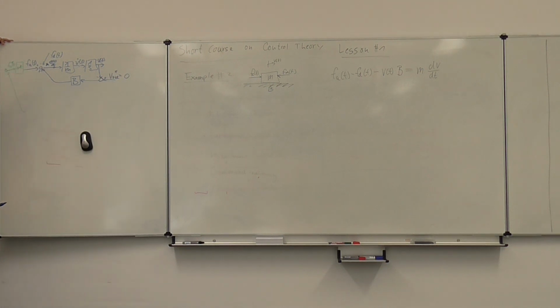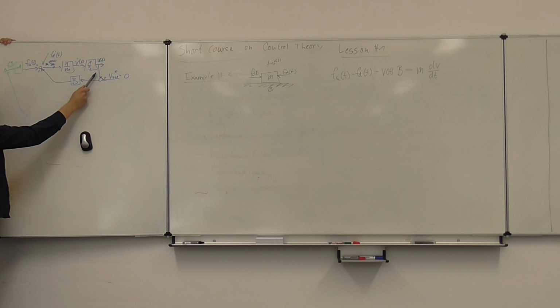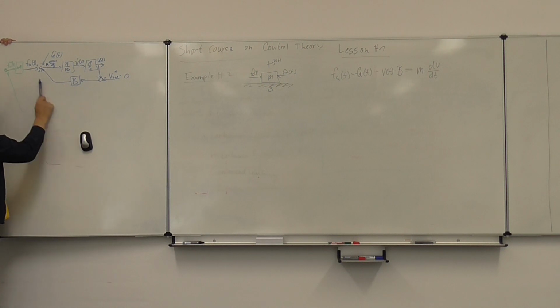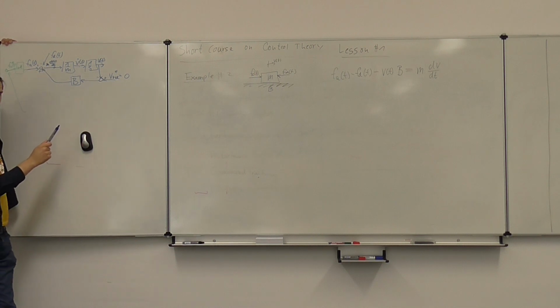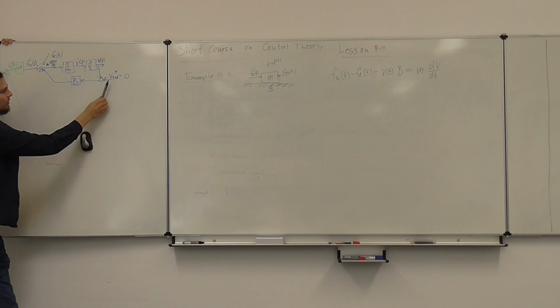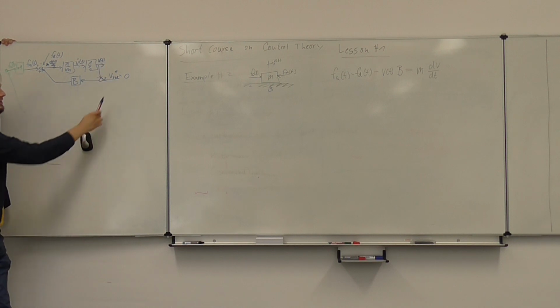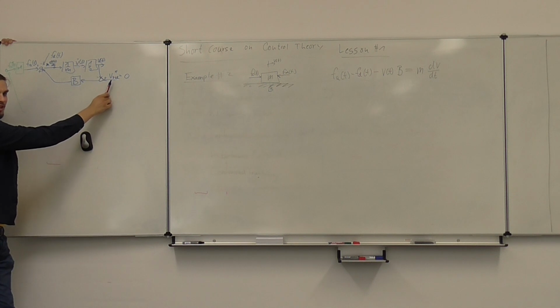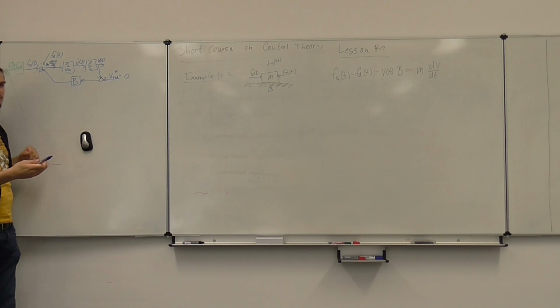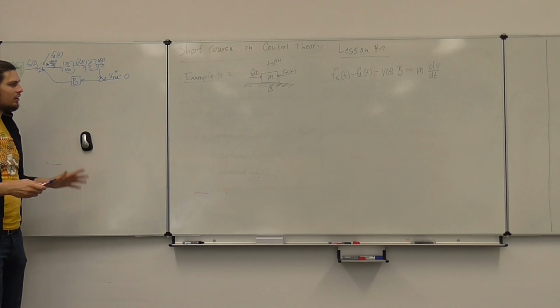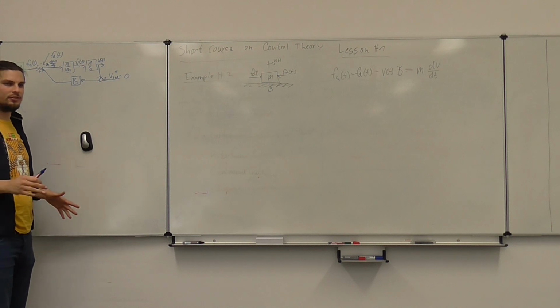How does this look like to you? You have a state, you have a reference that's 0, and you have a gain, and it goes into your manipulative input and changes something. It looks like a P control, right? So the state feedback basically looks like a gain for a reference that is 0. So it draws back your system by itself, which is common in almost every physical system.